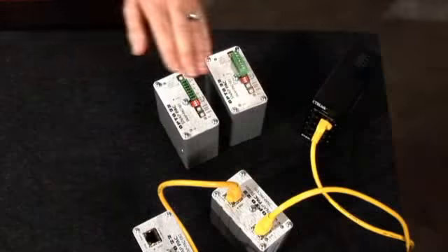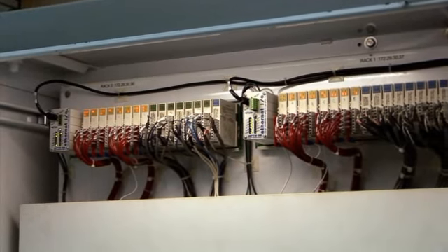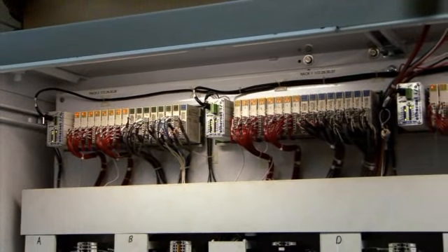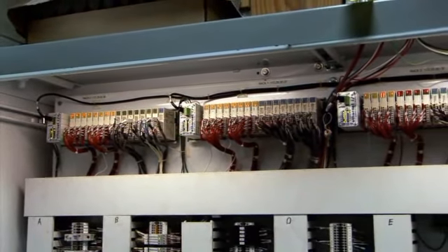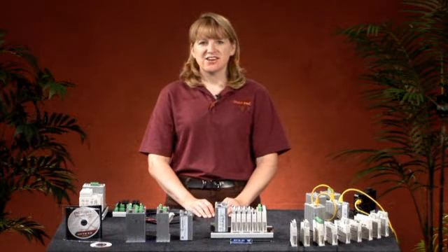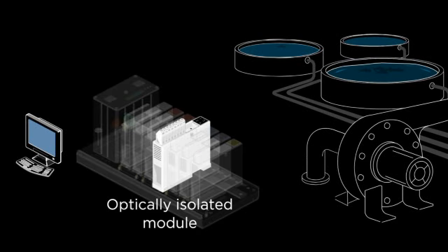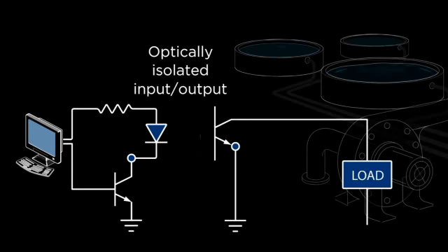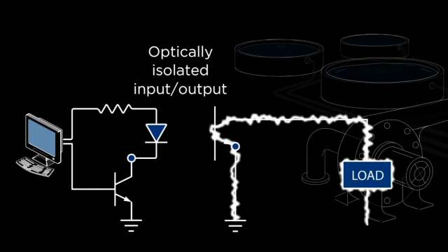The fourth part of the SnapPAC system is I/O modules, or input-output modules. They connect your various field devices, such as circuits, sensors, actuators, and transmitters. But Opto 22 modules provide more than just a connection. They provide optical and transformer isolation to protect your control electronics and reduce noise.